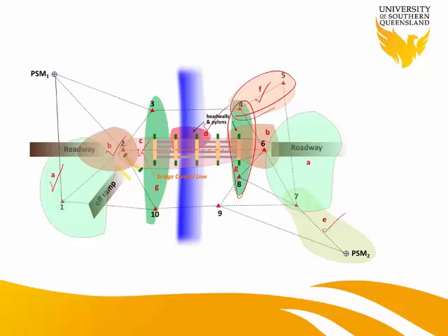What I mean is, obviously you don't need to remember all of those, but if you have been given tasks like that, you have to sit down and think: where is my major earthwork, A and B? What are the accuracy requirements for them? How am I going to check my head walls and pylons or piers? Where do I need to have the control marks for them? What's the accuracy I have to achieve for that particular control mark or particular area? What's the accuracy I need to achieve, for example, for bridge control lines in terms of alignment and distance, length and direction, basically? All those things should be thought through.